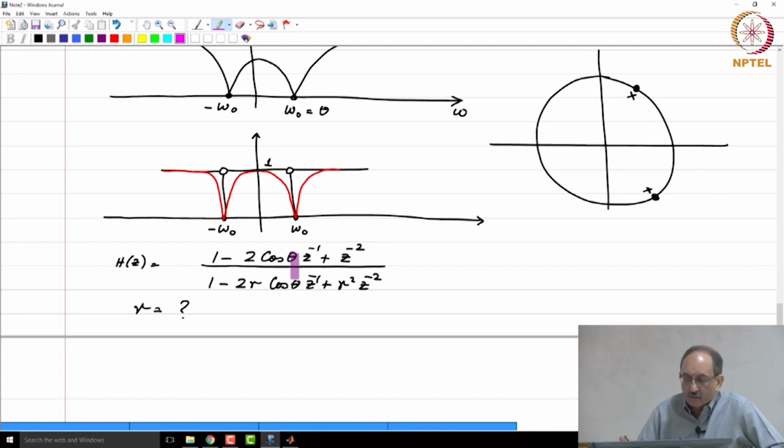What you are having in mind is, if you want to consider the impulse response and convolve it, then you have to truncate the impulse response to some limit. But that's not how you implement IIR filters. IIR filters will always have infinite duration impulse response, and the way they are implemented is, in the time domain, you will implement the difference equation.